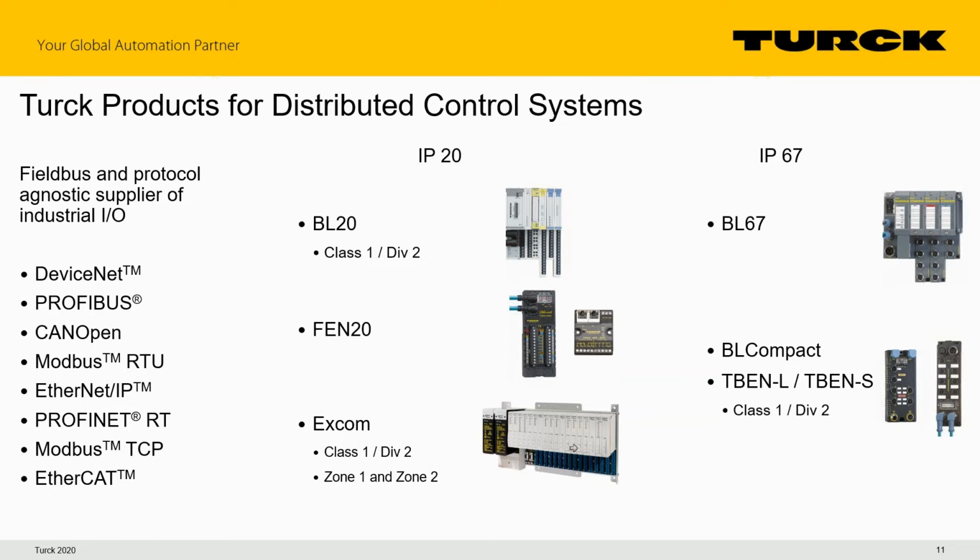The barrier is included in the I/O portion of this I/O system. It has the ability to use redundant power supplies and a redundant communications interface. So that makes it part of what is called high data availability systems. So very much oriented for the process industry, DCS systems, things like that.